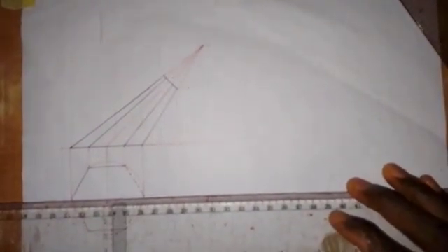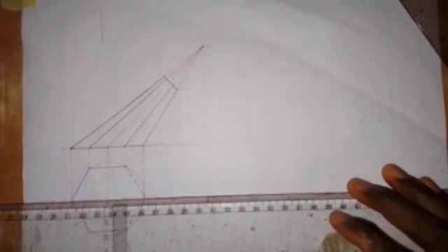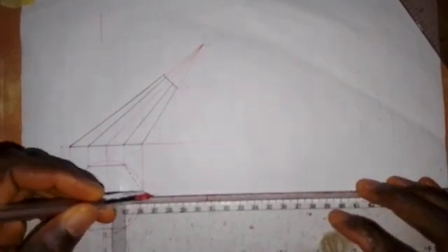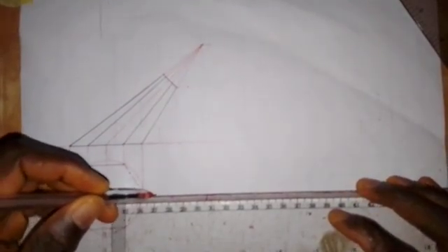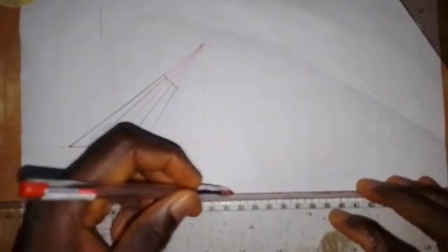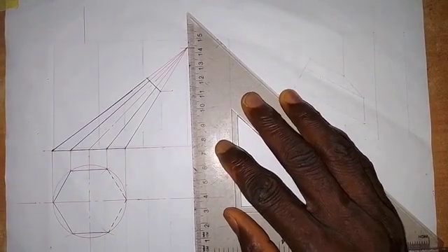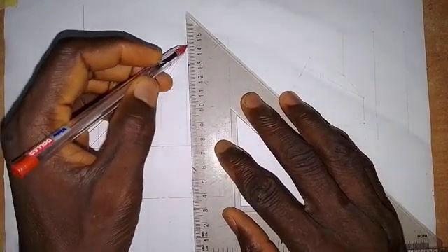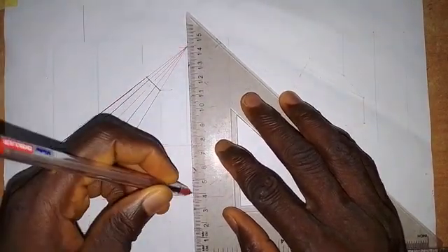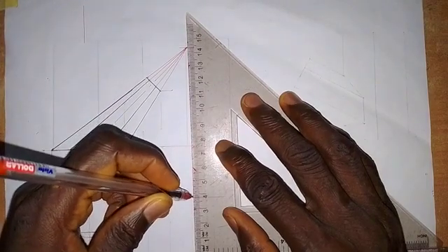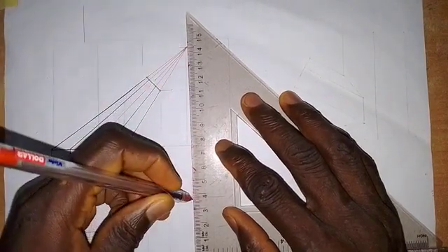For us to draw the complete plan, that's where we are going right now. So I need to extend this horizontal center line like this. Okay. So going on to draw the complete plan, I'm going to draw a vertical line from this point. A vertical line from here, but it's not compulsory. I can just mark it here. So that is this point here in the plan.